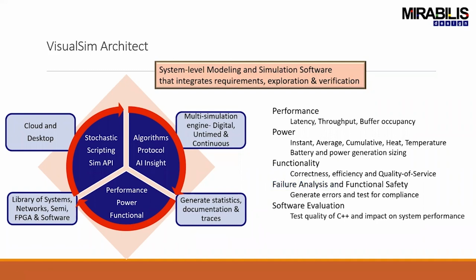So for example, even with the die, I can reduce the number of links, for example, or lanes. I could do it in such a way that the flit size becomes smaller midway through the design. Or I can have spurious addresses that are being sent across the die to die to see what happens to the overhead in the system as a result of doing something like that. So a variety of failures can be generated.